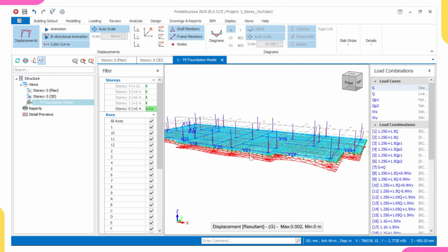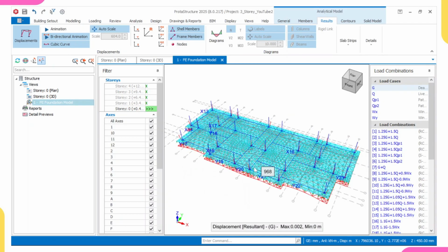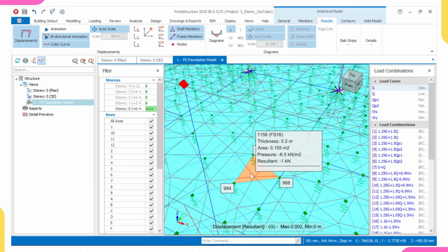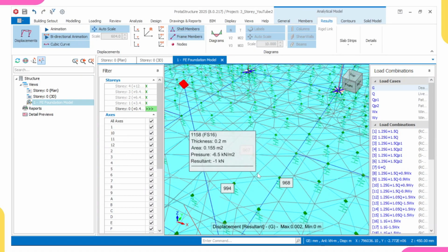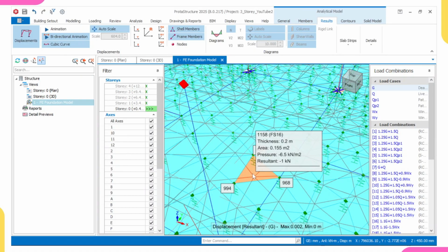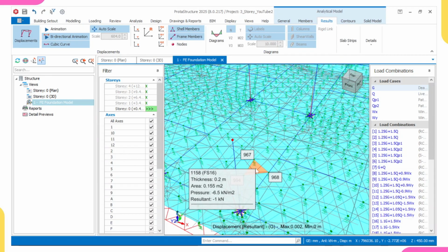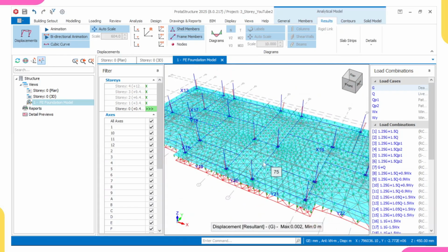So this is the analytical model. Look at what we mean by that shear element. If you see now, look at that 500 and 1000 that I'm showing you. Assuming I choose any value less than 1000 or less than 500, this triangle, this shear element, will be smaller. What it also means is that the analysis will be more accurate. But I will just advise you to leave it at default. So this is what we are having.